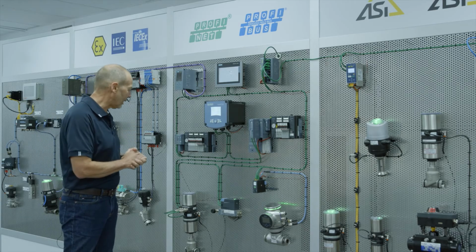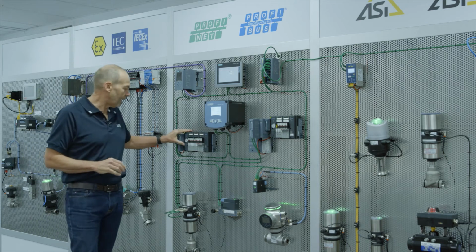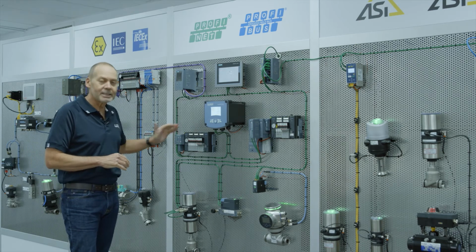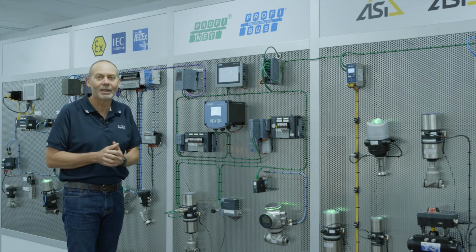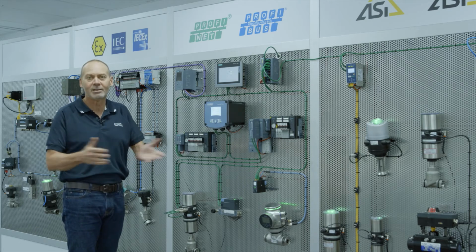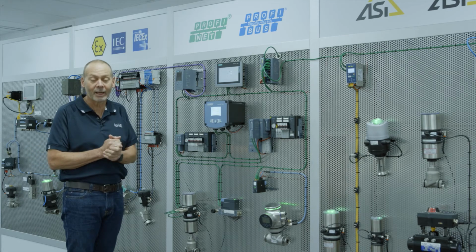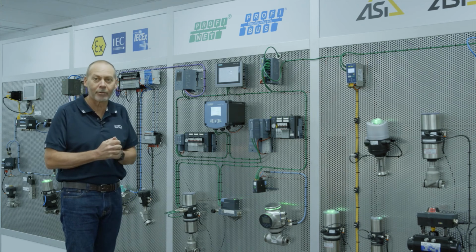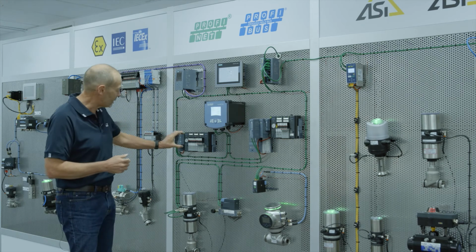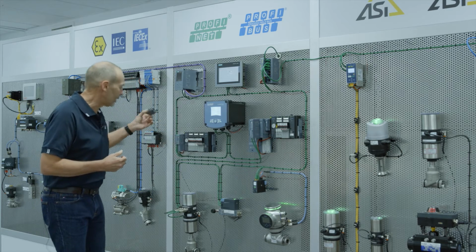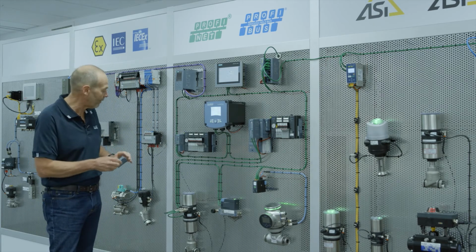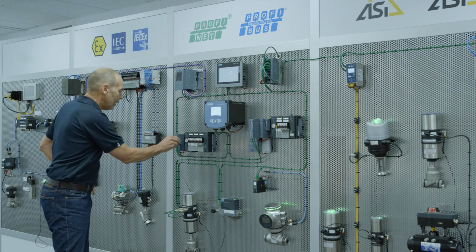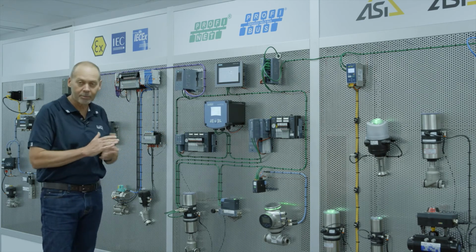One of the nice things about these different networks, in particular these I/O networks that we've integrated directly with Siemens, is the Hotswap functionality. We understand in the process market, we don't have systems we can turn off. If you're running a batch fermentation as an example, you can't say, oh, I've had a valve go down, I need to close my fermentation. You can't do that. So we've got to work out ways we can get back up and running in a fast way. All of the Siemens systems that you know have Hotswap functionality. So you can pull out the electronics on any I/O, whether it be analog, digital, or whatever, and you'll get an alarm, but when you re-plug it back in, it comes good again.